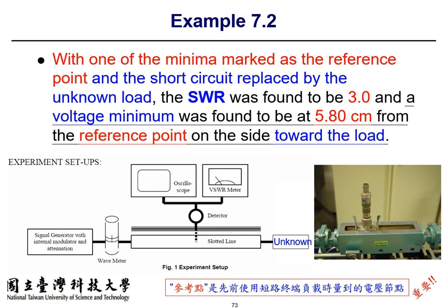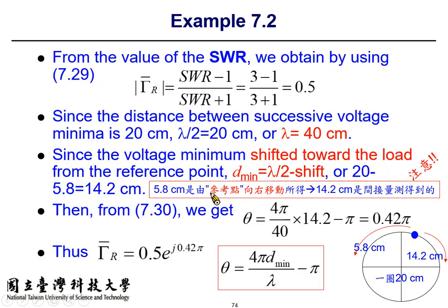And as you can expect, the complete standing wave phenomenon will go away if the attached load is not a short, or not an open, or not a fully reactive termination. As long as it has some resistance, you won't be able to have voltage zero on this line.